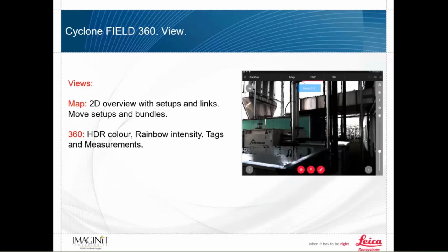In this view, I can also create tags, or I call them assets. Like I said a while ago, I can take a picture of an air handling unit nameplate and attach it to this picture, so that when I open up the point cloud in Register360 or Jetstream or the Jetstream viewer, that tag information is there. I can also measure in this view.